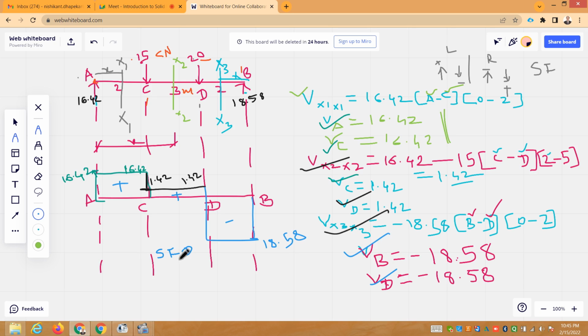So I think you might have enjoyed plotting the shear force diagram and understood the concepts. And as far as the sign conventions are concerned, if someone is plotting positive values below, then you will get a mirror of this. This will be below the x-axis, this value will be above the x-axis, but the solution will not make any difference. So in my next lecture, the same problem we shall take, simply supported beam with 2-point loads, and we shall try to plot the bending moment.